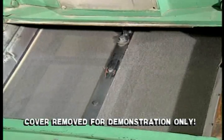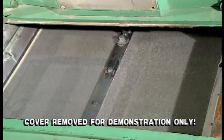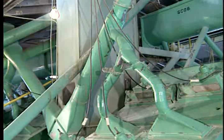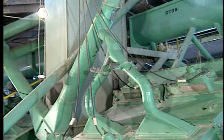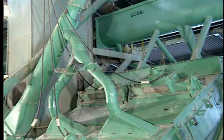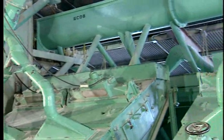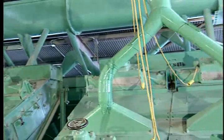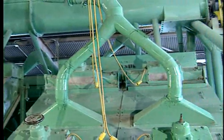Yes, there is a lot of mechanical activity in here, and we deal with this issue of dust escape by moving large volumes of air through the screen areas and through the ductwork connected to our screenhouse bag collector. If those collectors weren't working, this place would be one massive cloud of dust, and everything in here would be covered with a fine film of material we're trying to avoid.